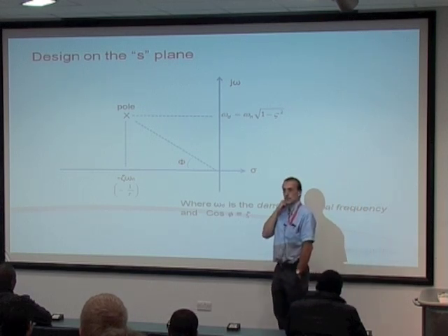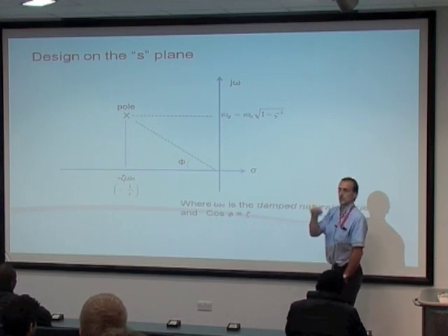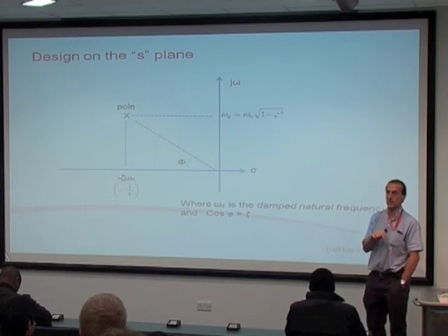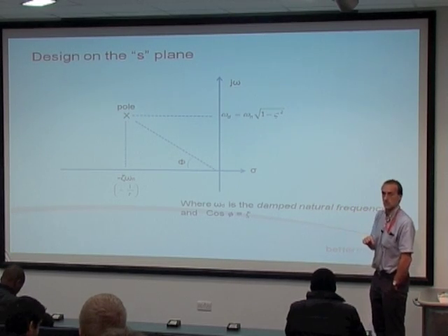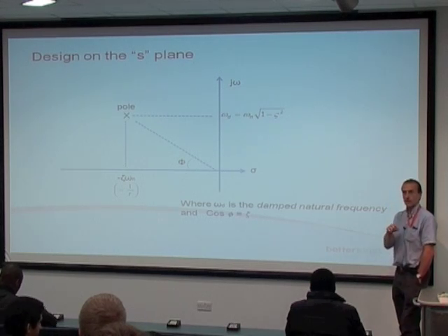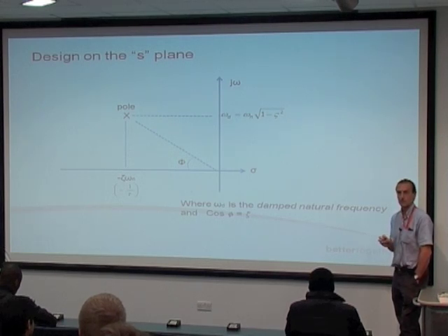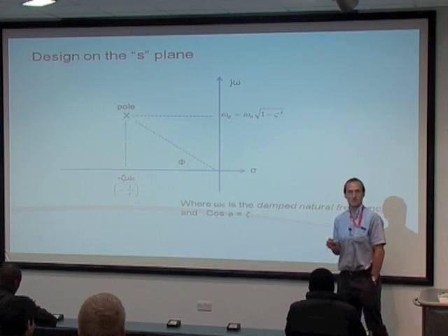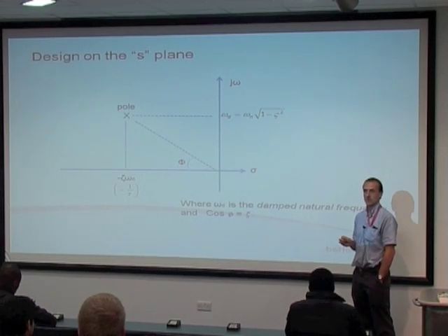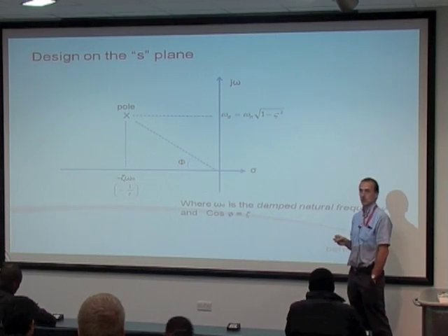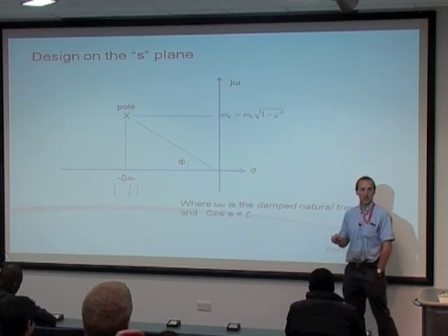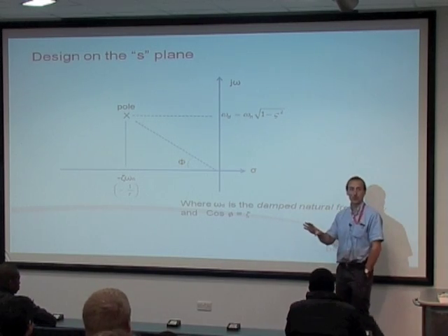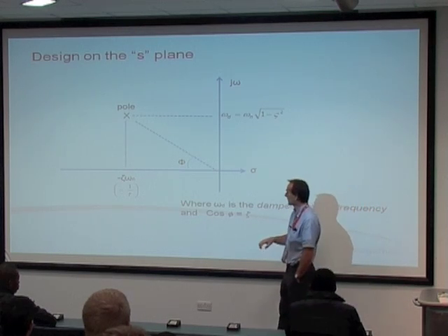Yeah, after one time constant, our first order system gets to 63% of the final value. How long does it take it to get to 95%? Do you remember? This is our definition of the 95% settling time. No, maybe not. It's too long ago. That's okay. I'm going to get you with this one because this week's tutorial sheet is a revision one. You'll have to look back through your notes.